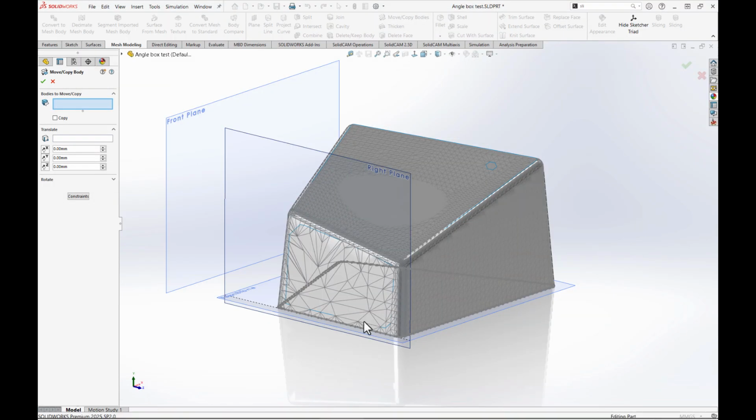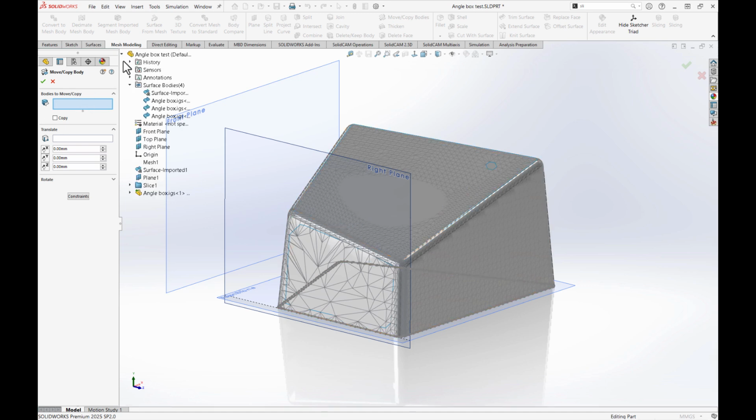But if you've moved the mesh slightly during the import process or just after, then you'll have to take a note of how you moved it and in what directions, X, Y or Z, and just move the IGES features by a corresponding amount. And the way that you would do that is you kind of browse and find what the IGES features were called.